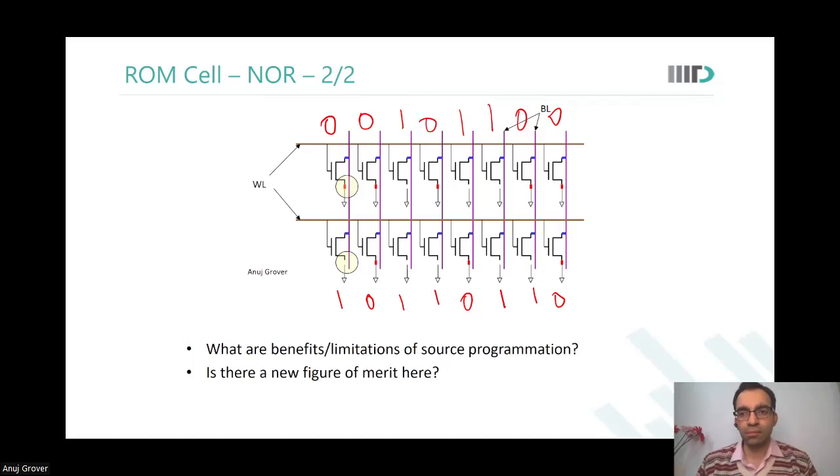Sir, what I understood about load is that there would be a capacitance corresponding to the drain position of the transistor. Wait, Vaishnav, is there a capacitance that is related to the drain and source region of an NMOS? Yes, sir. In DVD, we have studied about that. What is that capacitance? We looked at the sidewall capacitance and the bottom capacitance.